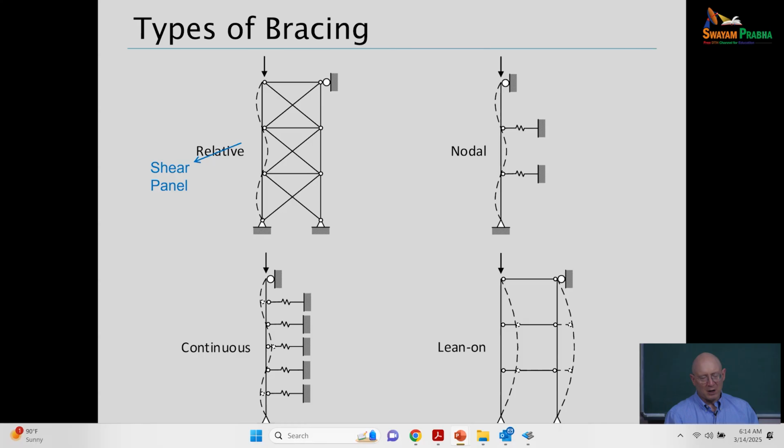panels. Then there's nodal bracing, so that's at the top right, which is now referred to as point bracing in the AISC standard. Or if we want to be more wordy about it, a discrete grounded brace. So the difference here is, you could say, a similar column to what we were just looking at, with two intermediate brace points and braces at the ends.